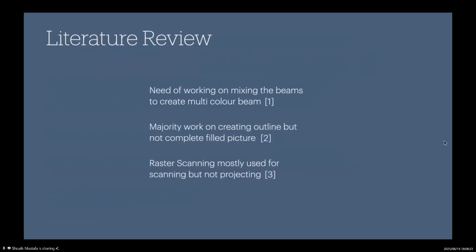And basically what our review told us was that there was a need for mixing the beams and creating an RGB setup. And also we realized that there were a lot of outlined laser projectors, but there weren't any that would allow us to project a full picture with all of the colors. There are, but they are usually dependent on very small chip sizes using DLP and the MEMS devices. So what we tried to do was a bit on the hobbyist scale as well.